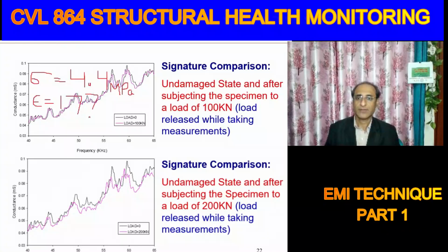177.6 microns, right? 177 is okay. So this is the strain level we are subjected to in compression. At 177 microns, this implies that the cube is undergoing very small micro cracks. And when we are doubling it, it will be 2 times 177. So definitely when the stress level is double, the cracks will further expand, and this is reflected partly in the signature.